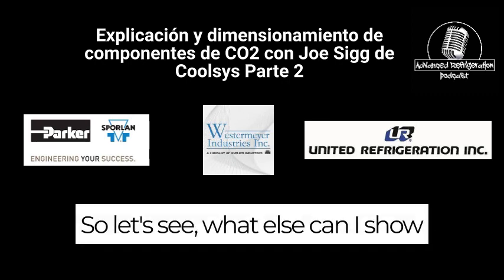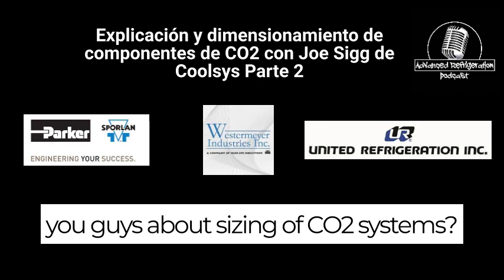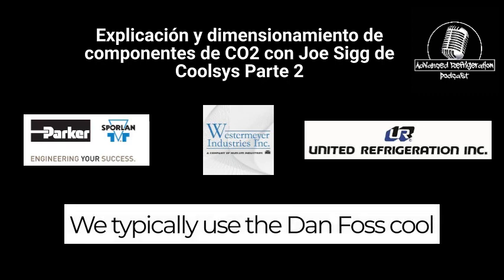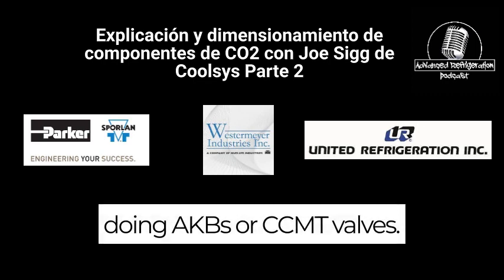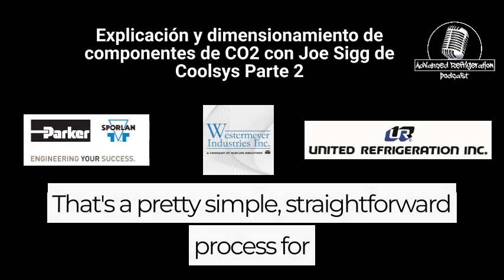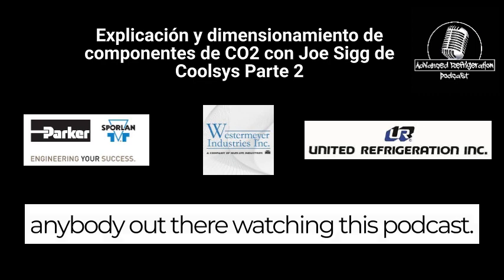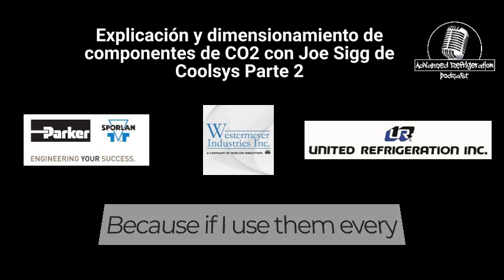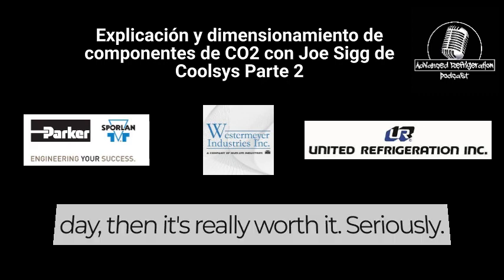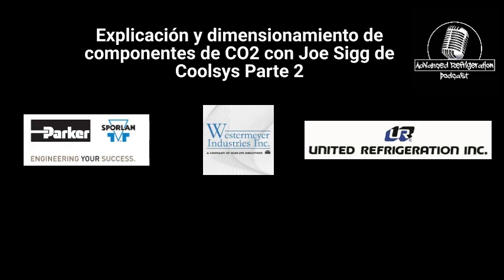So let's see. What else can I show you guys about sizing of CO2 systems? We typically use the Danfoss Coolselector software for valve selections when we're doing AKVs or CCMT valves. That's a pretty simple, straightforward process. For anybody out there watching this podcast, if I mention a software, please go out and download it and give it a try, because if I use it every day, then it's really worth it.